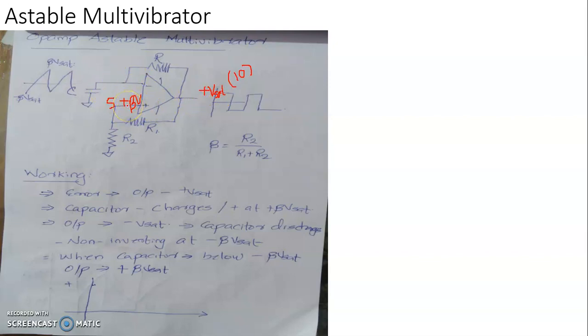Then also high voltage is given to the non-inverting terminal. Output will be at plus V saturation. It becomes 2, 3, 4, 5 and the very next moment this voltage becomes 5.0001. At that instant, the voltage given to the inverting terminal exceeds that given to the non-inverting terminal, so the comparator output will sharply and suddenly switch into minus V saturation.